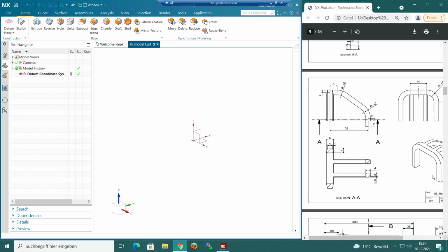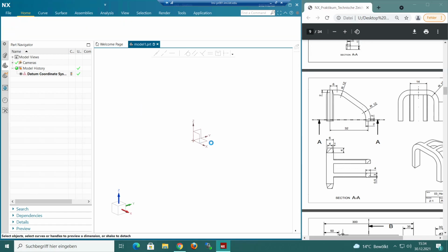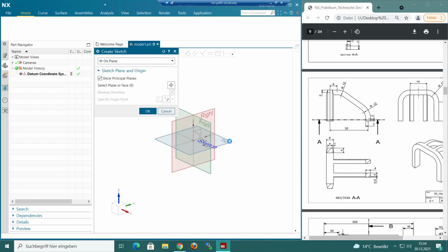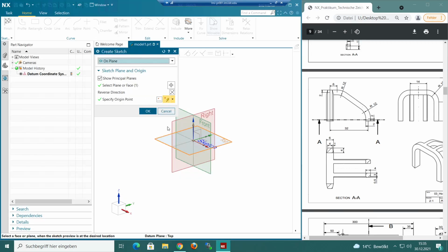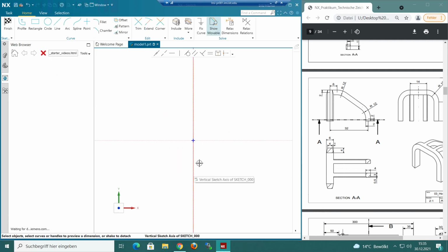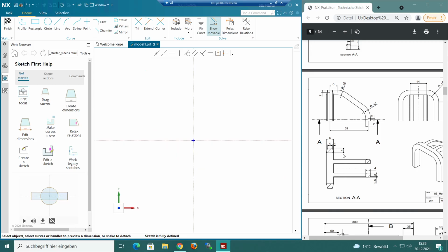And the first thing is modeling this, as already said, and we therefore have to start with drawing this cut right here. So I'll select the y-x axis, which is the top axis, and the tutorial is annoying. Okay, so select that one. And now drawing this shape is pretty easy. We see the height is 4, that smaller side is 4, and the bigger side is 6. Therefore, we have 1 in between, so it's symmetric.